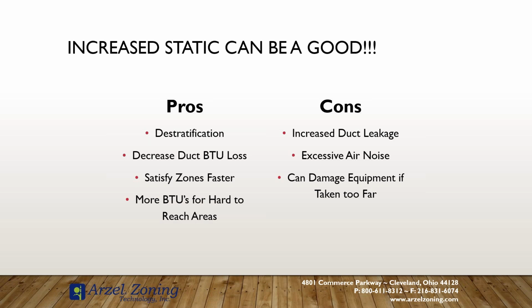But some of the cons that we can have, if the ductwork's not sealed, we increase our duct leakage. So we're going to push more air out the drive seams, out the clip seams. We're going to push more air out of the connection point for takeoffs that aren't sealed up, or the gussets on our elbows, things like that. So it can increase duct leakage if we're not sealed up. Now, while some duct leakage is acceptable, if we have significant duct leakage, then we're really wasting the benefits that we would have from that increased static, because we're now pushing air into unoccupied zones, or we're potentially pushing air into unconditioned zones if the ductwork runs through an unconditioned area outside the building thermal envelope.